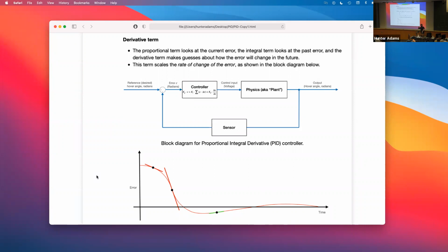If you get this tuned just right, it'll really quickly approach the desired angle and overshoot a little bit. You can trade rise time for overshoot here. Maybe you want a faster system that overshoots more, or a slightly slower system that overshoots less. I'm asking you to aim for critical damping here, where you want the system to overshoot and settle in about half a cycle time. Something like that. We'll look at plots of it.